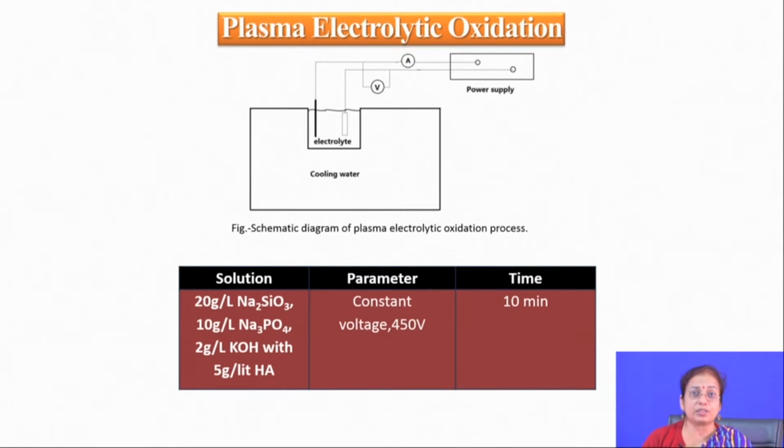During the off cycle, the transported metal melts, and then again in the on time it gets oxidized. So, in each on time there is an oxidation process, and in off time there is basically the transportation of molten metal from below the oxide surface to the surface. Like that, this process proceeds in a layer by layer fashion.